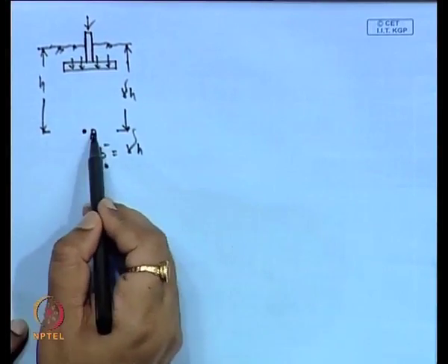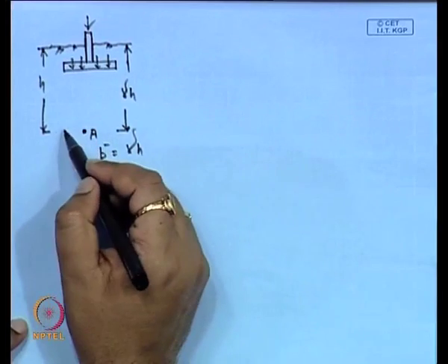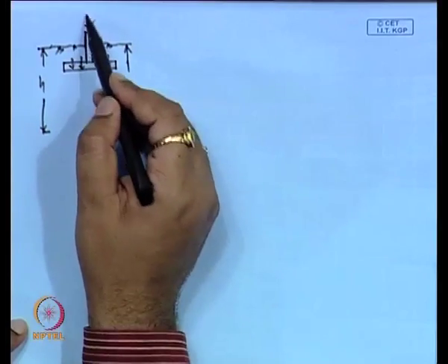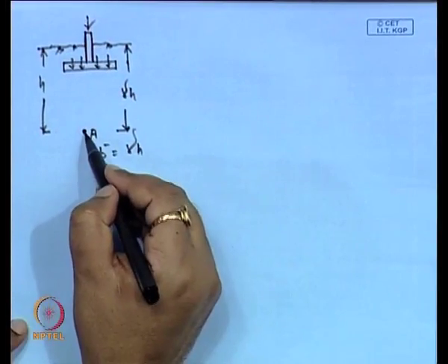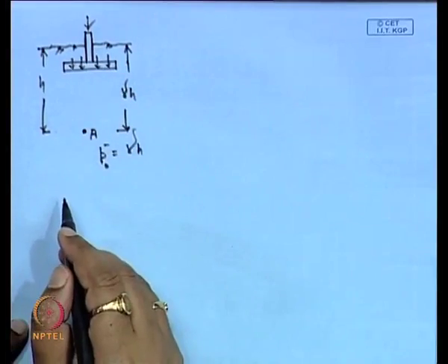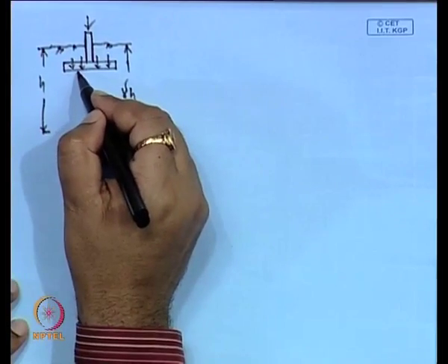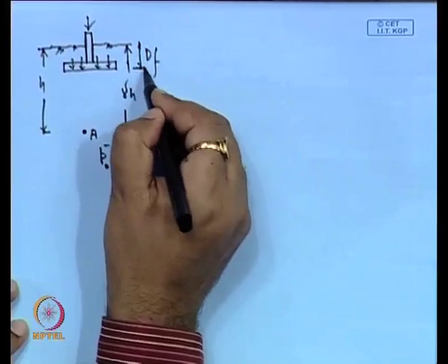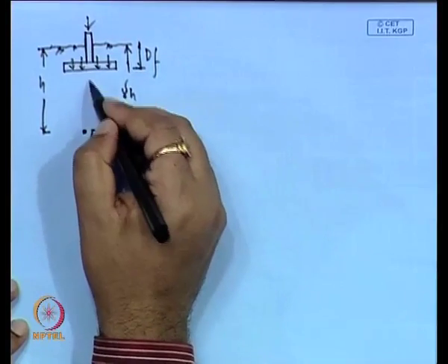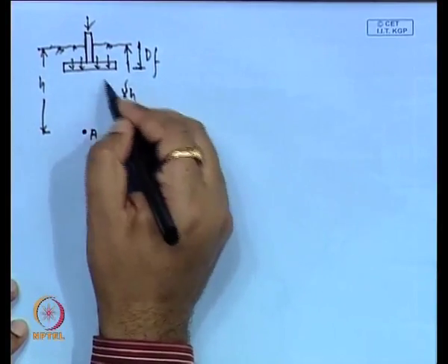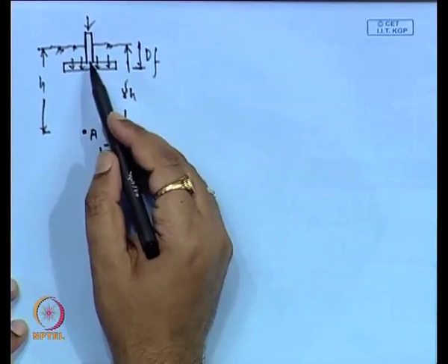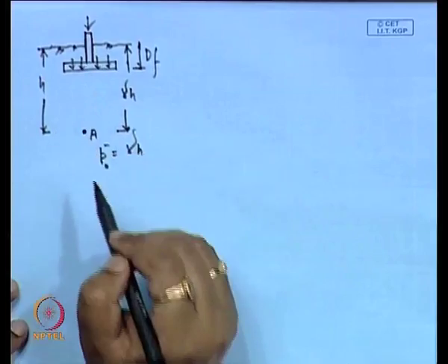This is the increment of load due to application of the foundation load at any depth below the base of the foundation. Suppose this is Df, the depth of the foundation. From this zone, the stress increment will occur because of the foundation load application.